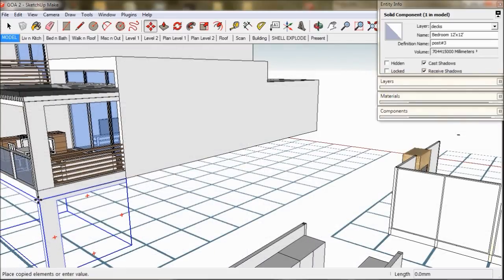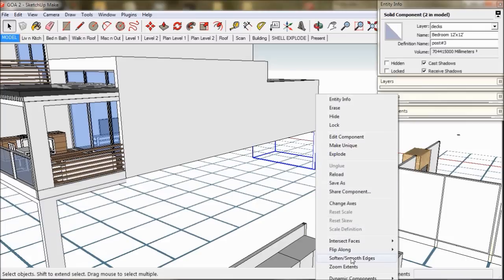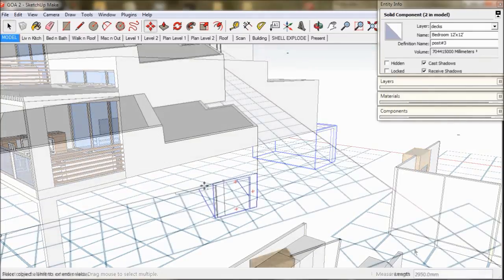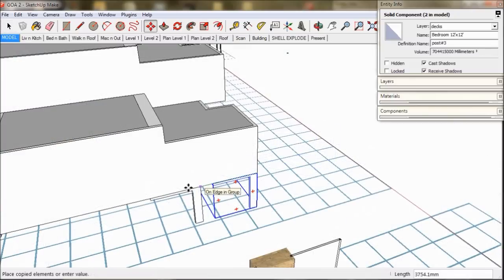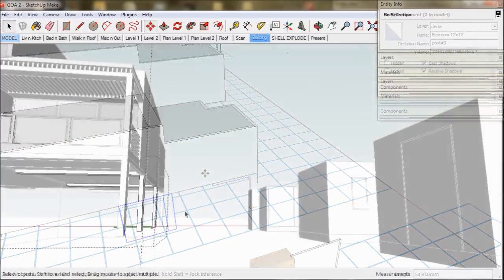So we move our copy down 3 metres or 10 feet and make a copy for the other corner and flip it over to suit. We then make another copy for intermediate columns, make them unique and push-pull them into shape.